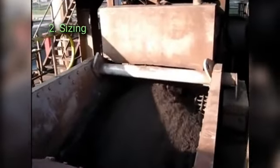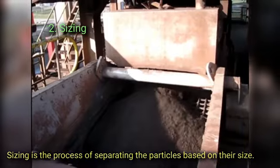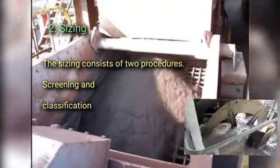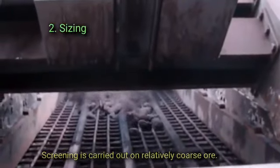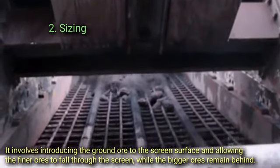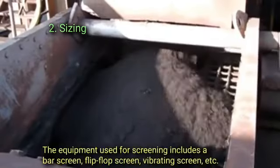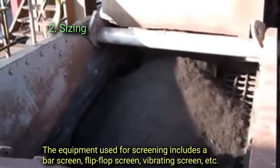2. Sizing. Sizing is the process of separating the particles based on their size. The sizing consists of two procedures: screening and classification. Screening is carried out on relatively coarse ore. It involves introducing the ground ore to the screen surface and allowing the finer ores to fall through the screen, while the bigger ores remain behind. The equipment used for screening includes a bar screen, flip-flop screen, vibratory screen, etc.